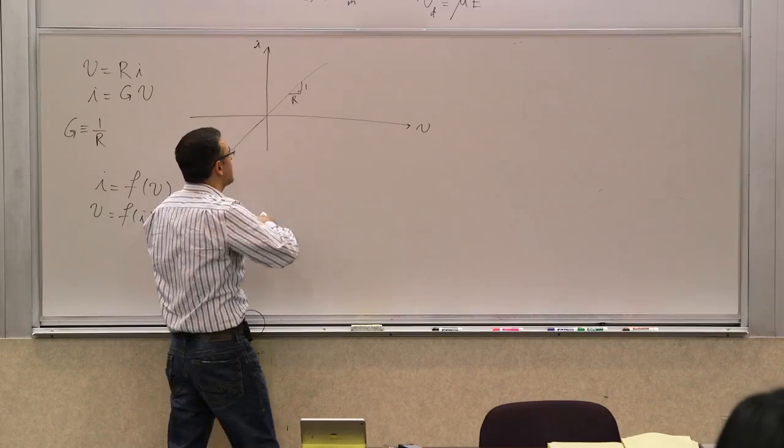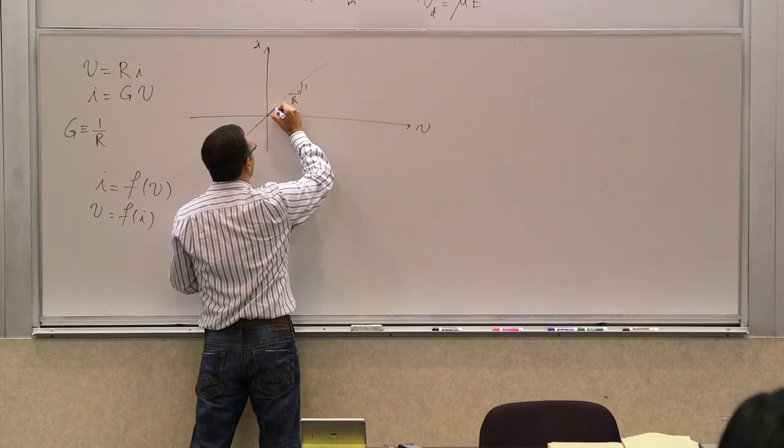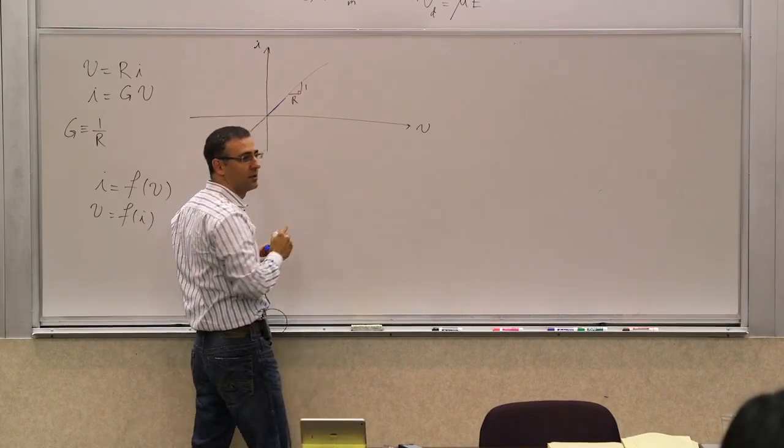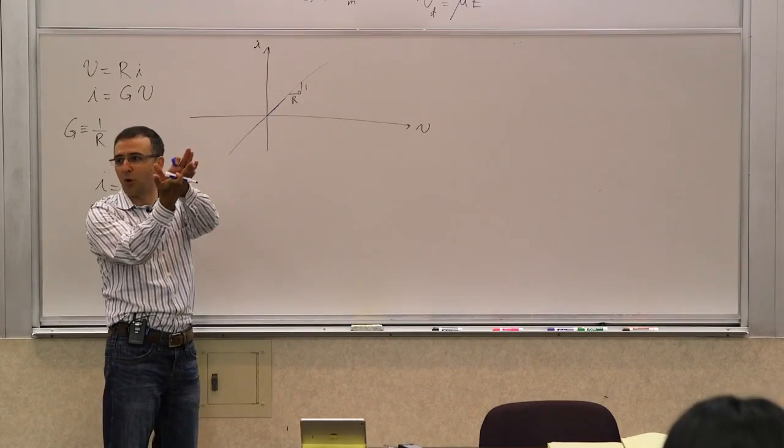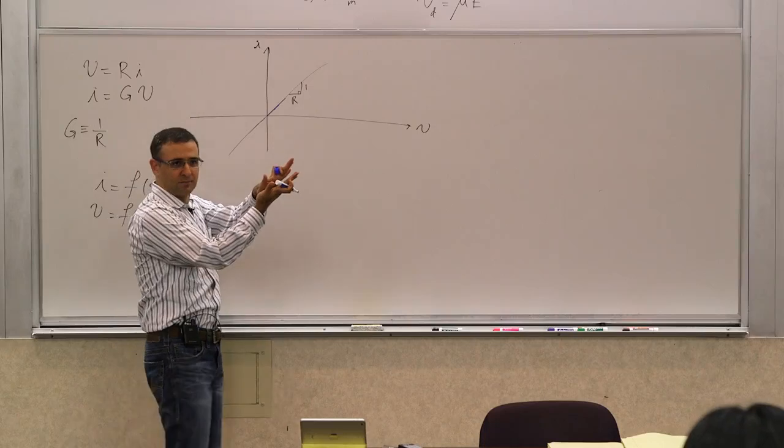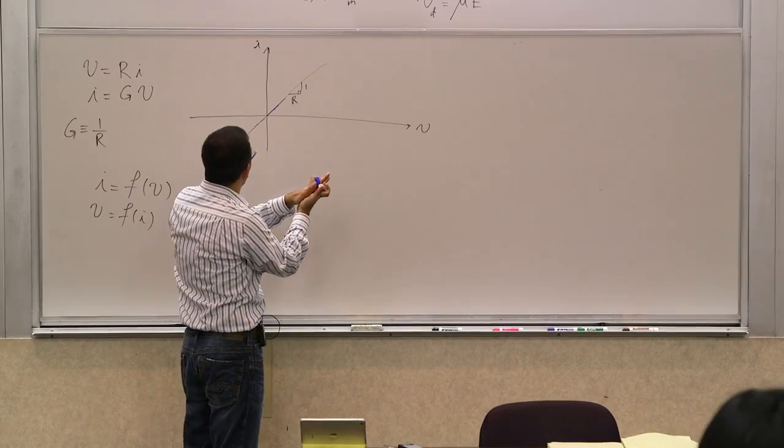You will see that initially, as you increase the voltage, the current goes up linearly. It may be a little bit off, because it may say 100 ohm but actually be 98 ohms, or maybe 103 ohms. There's some tolerance and variation on this.